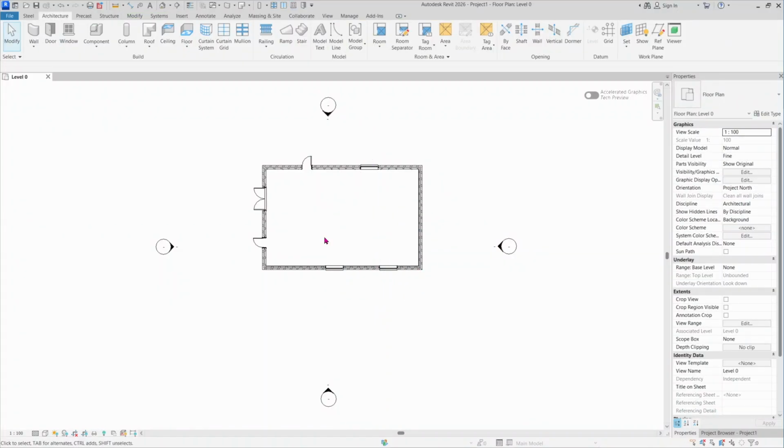When you are using a tool in Revit, you want to exit. Remember the escape rule. If you press escape one time, you do not completely exit the tool. Revit keeps the tool active so you can start a new segment. However, if you press escape two times on your keyboard, you will completely exit the command and return back to the selection cursor. And when you're using Revit, you will always use double escape.